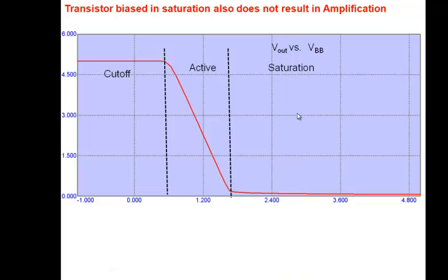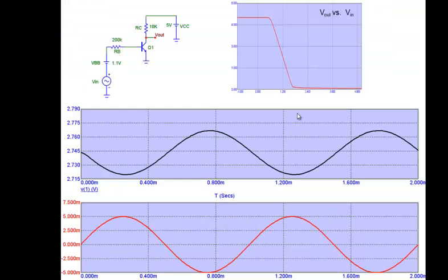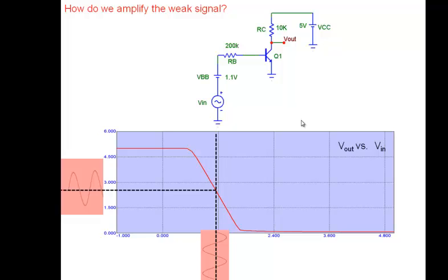Now, it's also telling you the following. Let me go back here to this picture here. It's telling you that this is where I bias here. This is the bias point, operating point. Now, when I apply my signal, what happens to my transistor? Transistor goes a little bit down and then goes a little bit up here. So it's moving along that axis, right? Because the net voltage that you see here is 1.1 plus 5 millivolt. Okay, so it's moving down and it's moving up, right?